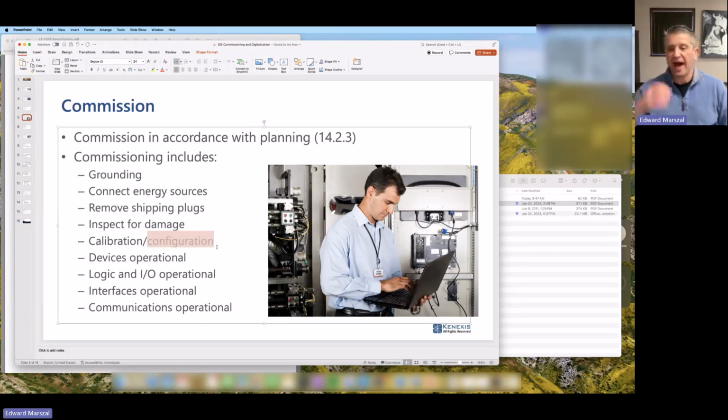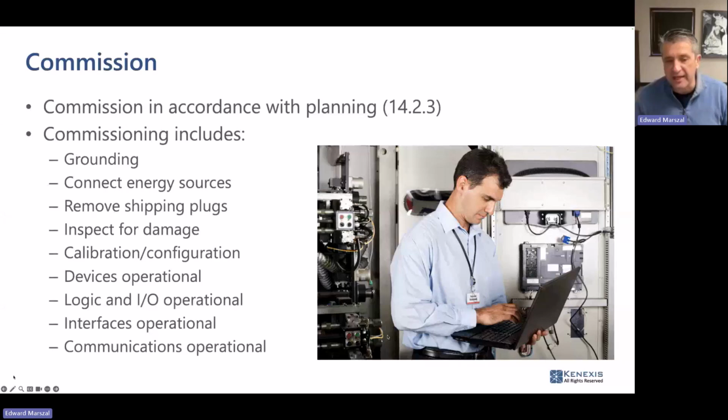It's not just an outside visual inspection. You're going to want to plug your HART communicator in and check the parameters against the spec sheets to make sure that everything on the spec sheets is true. Okay, so kind of going down the road, the next thing in the configuration process is that logic and I/O are operational.